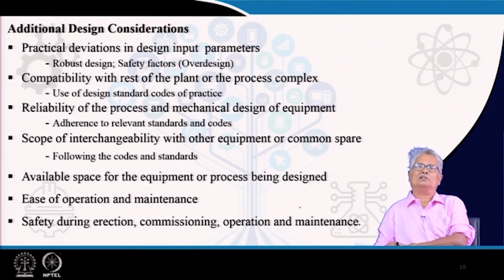There are codes which relate to the material quality, there are codes which relate to the design of pressure vessels, there are codes which relate to the design of heat exchangers and columns and other things. And definitely making a design as per the code gives us certain advantages like interchangeability of equipment, reliability of equipment, and following a uniform code will definitely attract less amount of insurance price, which is normally, particularly for hazardous plants, a reasonably large fraction of the operating cost.